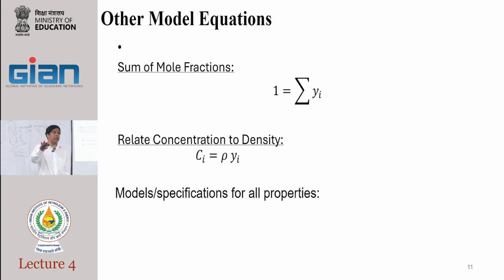If you have never used Aspen Custom Modeler, which is what AdSim is built on, the solver solves everything together. MATLAB doesn't do that. In MATLAB, you have to call a routine like fsolve and say solve this system of equations. But for Aspen, the solver comes at the top of it, so it grabs everything and solves it. You don't need to worry about it. You don't need to say solve this one, this is my initial guess. You don't need to tell it anything. It will automatically grab everything and solve it in one shot. That's a fundamental difference between the two.